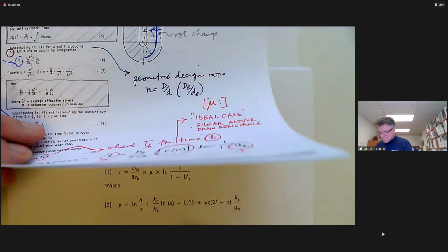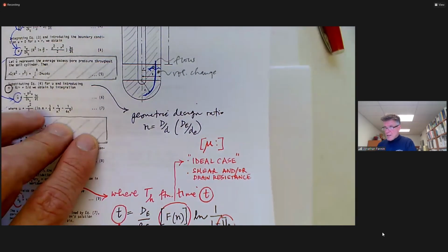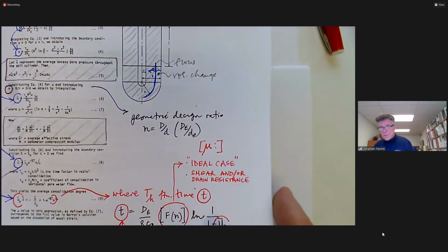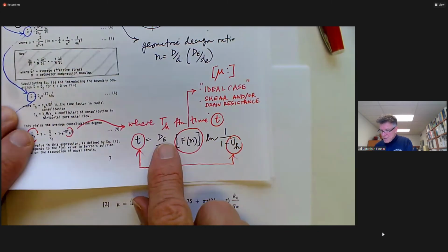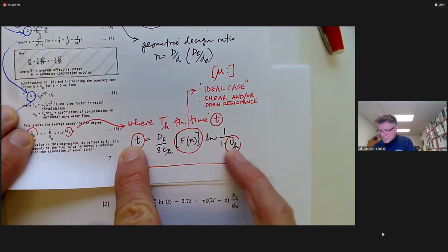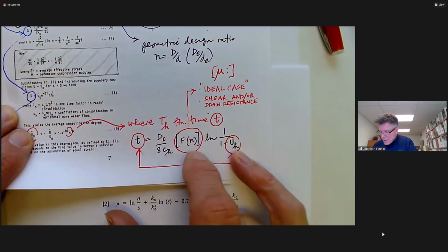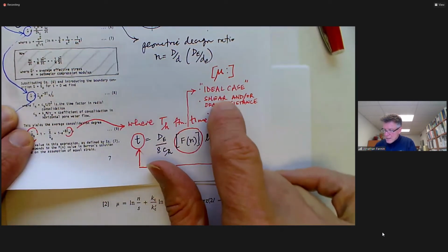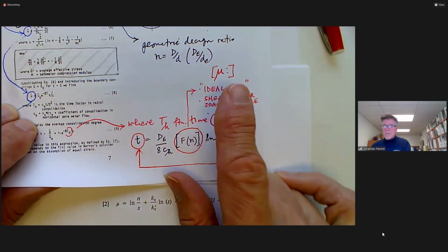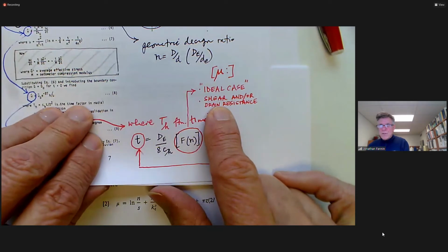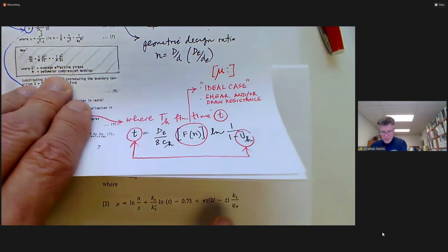Okay. So, interim summary. Hansbo does his work in the 30s, 40s. Wick drains clearly work. Hansbo comes along, gives us this derivation, a relation between time and degree of consolidation, given the nature of the soil, given the spacing of the drains, and a function that's taking account of assumptions as to how much additional disturbance and impedance may arise from the drain itself.